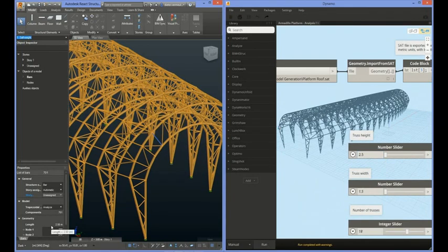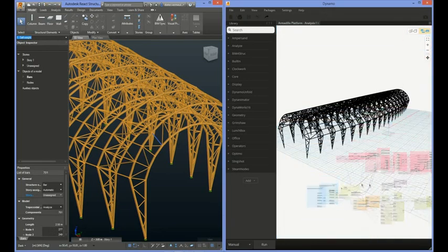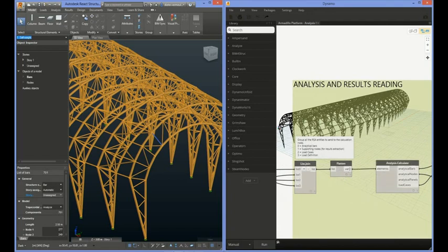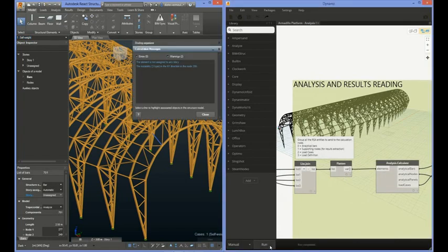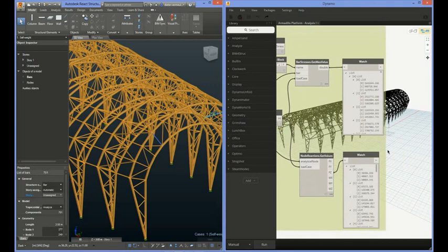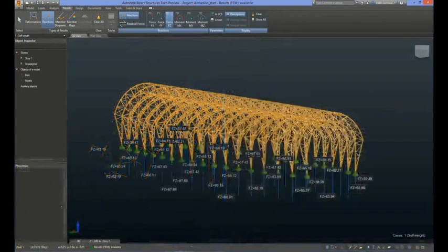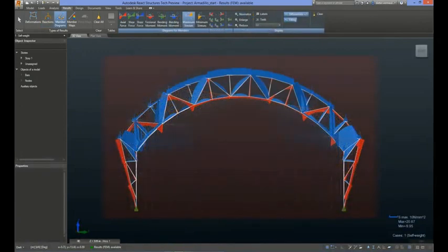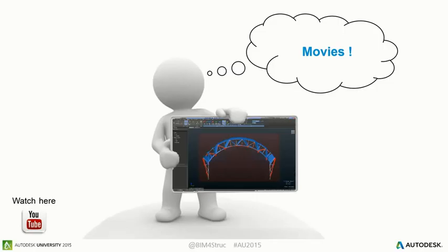It's just because I took such a small population, just for this purpose, for the presentation. So keep that in mind, use a big population to start with, at least 10. Yeah? But this one is just trying to test it to see, is it working, yes or no? Because you can also get results like null. So no values. Then it means it doesn't have worked. It doesn't have generated any of the elements because your domain was maybe not set or your variables were not okay, or your script function is not working. So that's also a problem.